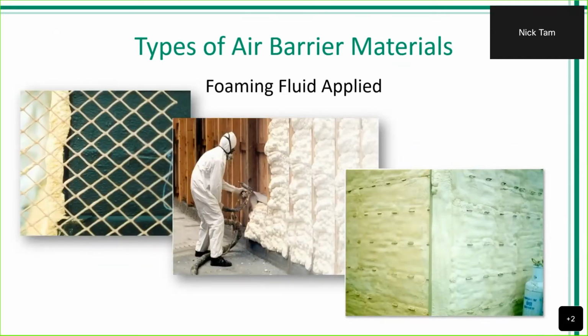And then we have our foaming fluid applied materials. So what we consider the holy grail, because it's a little bit of your do it all. It's going to waterproof. It's going to provide thermal resistance, especially when it comes to wood frame structures. And it's also going to be in either open cell or closed cell as it relates to the permeability of the material. So a really good product to use, especially when we think about wood frame structures, not used as much with steel just due to thermal bridging, but with them, they do come at higher cost, but depending on the budget of your owner and the makeup of your structure, these could be a really good option.